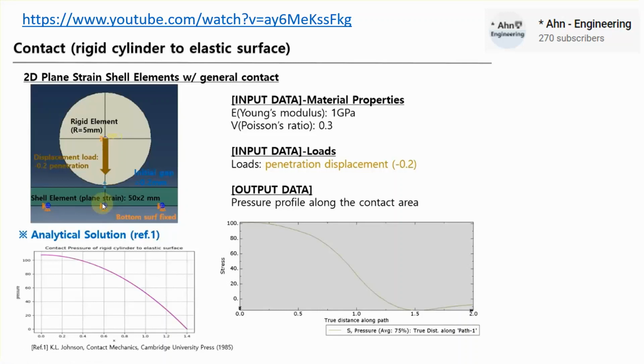The problem is done with a plane strain assumption, which is not available incidentally in the 3D Experience. Neither plane strain nor plane stress are available there. So what I have to do is to solve this thing as a 3D problem, and then try to make sense out of that.